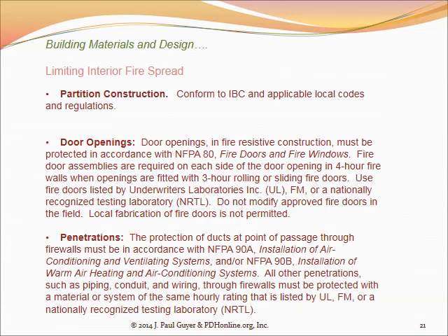And so if you have an air conditioning duct, for instance, that passes through an exit corridor, then you have to do things like put fire dampers in the air conditioning duct at the point where it passes through the wall into the 2-hour rated corridor. And then in the event of a fire, a fusible link typically melts, the fire damper automatically closes and is of such a construction that it will maintain its integrity for 2 hours and keep the smoke from moving from one area to another.